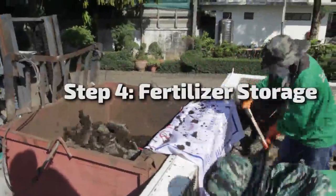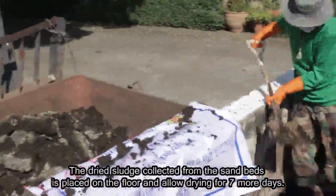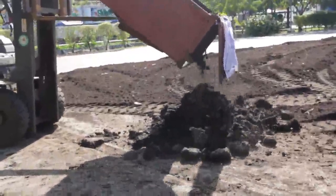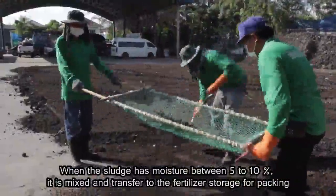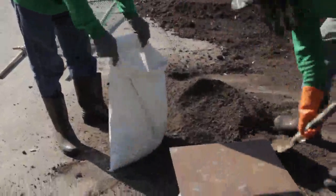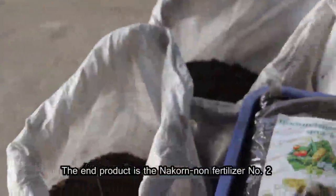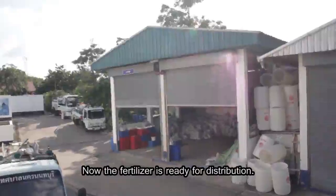Step 4. Fertilizer storage. The dried sludge collected from the sand beds is placed on the floor and allowed to dry for 7 more days. When the sludge has moisture between 5 to 10%, it is mixed and transferred to the fertilizer storage for packing. The end product is the Nakhon Non fertilizer number 2. Now the fertilizer is ready for distribution.